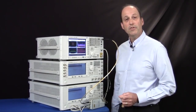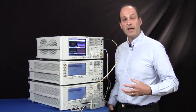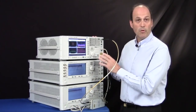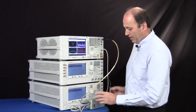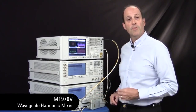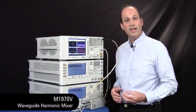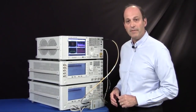Now, to analyze our signal, we'll be using the EXA signal analyzer, which is part of Agilent's family of X-series signal analyzers. This happens to be the 44 gigahertz model, and it has the external mixing option. The external mixer we're using is right here. That's one of our smart mixers, and we call it a smart mixer because it has onboard memory that has all the correction values for this particular mixer stored inside.